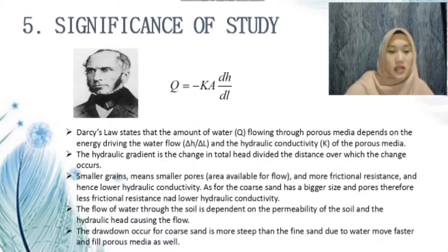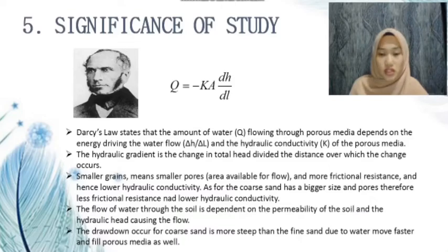Significance of study. Darcy's law states that the amount of water flowing through porous media depends on the energy driving the water flow and the hydraulic conductivity of the porous media. A hydraulic gradient causes water to move, and is the change in the total height divided by the distance over which the change occurs.